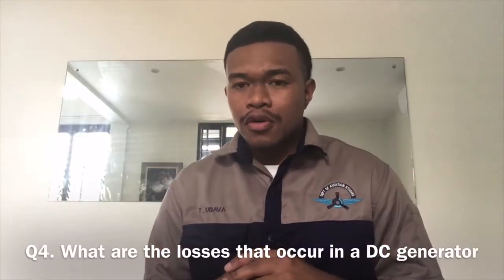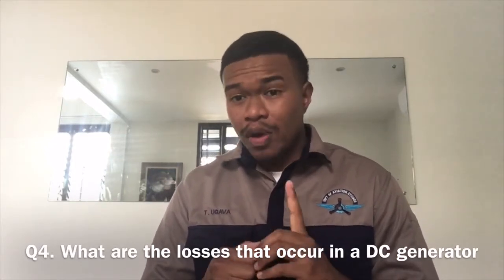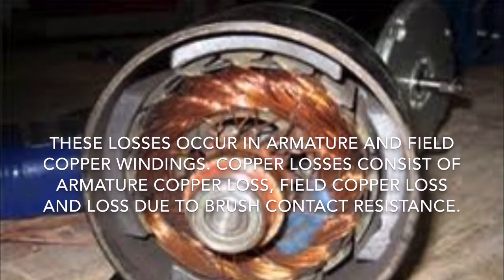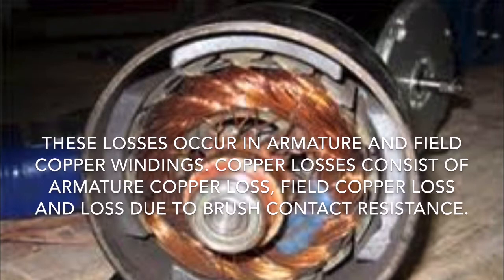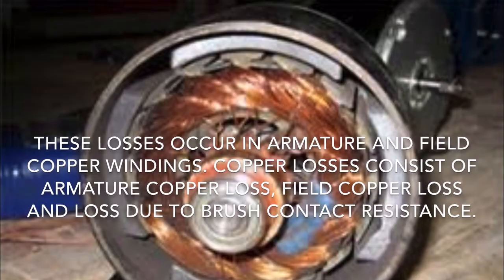Question number 4. What are the losses that occur in a DC generator? Number 1, we got copper loss. These losses occur while current flows through windings and are of 3 types: armature copper loss, field winding copper loss, and losses because of brush resistance.